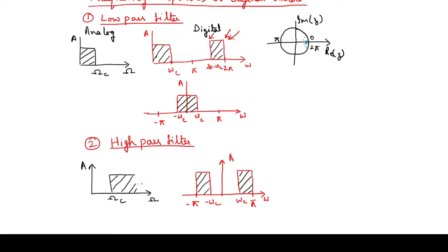Using windows allows us to design a filter whose transition periods increase gradually and also decrease gradually. When there is a gradual increase or decrease in the amplitude response of the filter, the Gibbs phenomena is automatically reduced significantly.